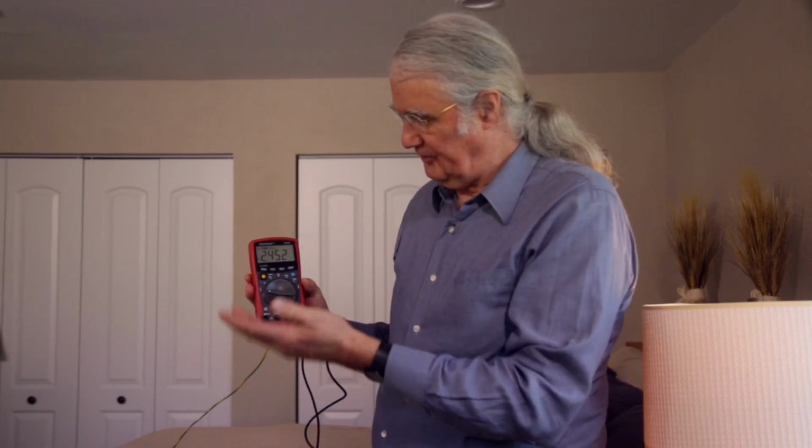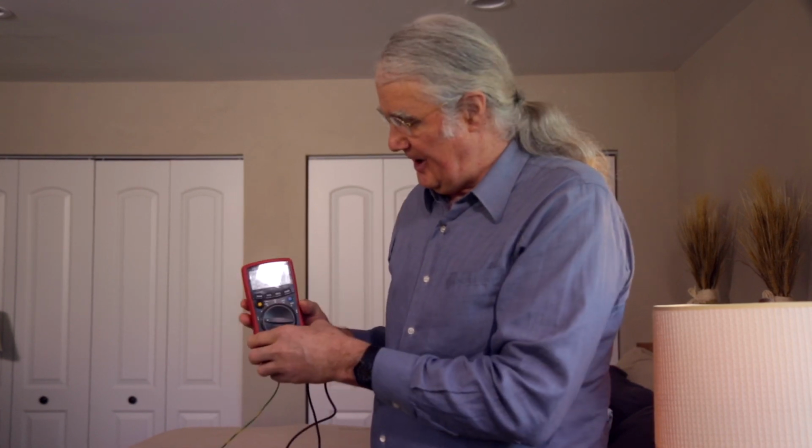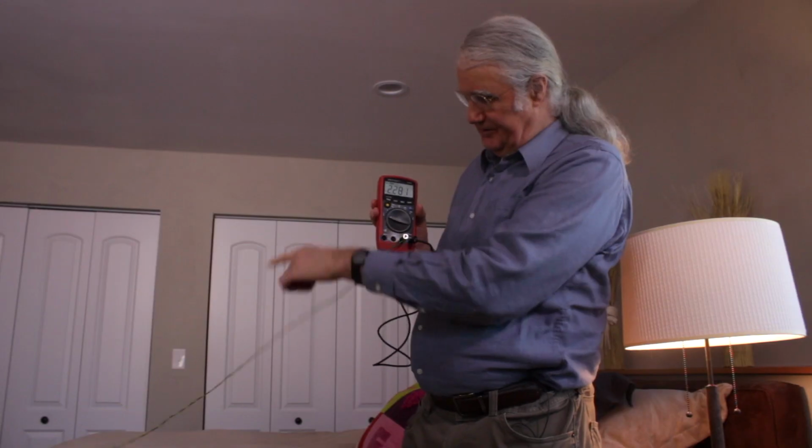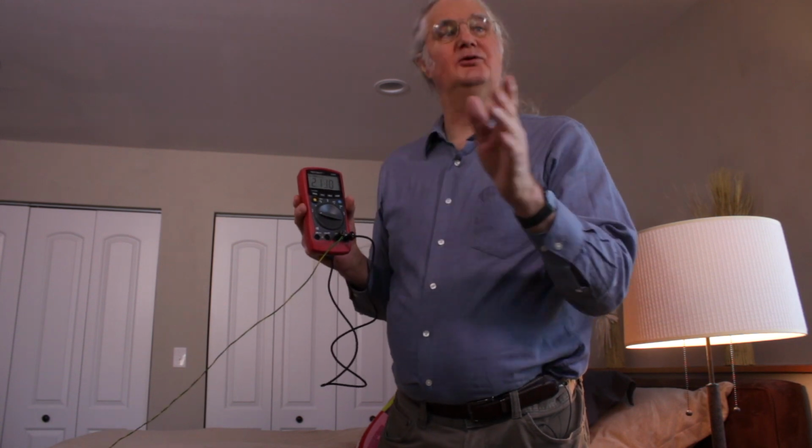My colleague Oram Miller is now going to demonstrate electric fields via a body voltage meter. So what I'm demonstrating here is another meter that we use for measuring electric fields. This is the body voltage method, and of course you all recognize that this is a simple digital multimeter. We have it set to volts AC, not DC, and we have one of these leads connected to the ground of an outlet on the other side of the room, or we can run it out a window to a stake in the ground. So that's our reference. We're referring the electric field exposure of this area to Earth.